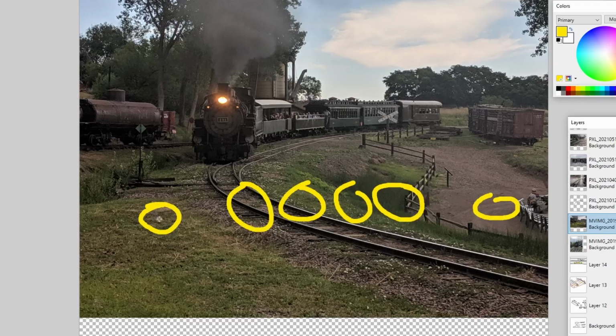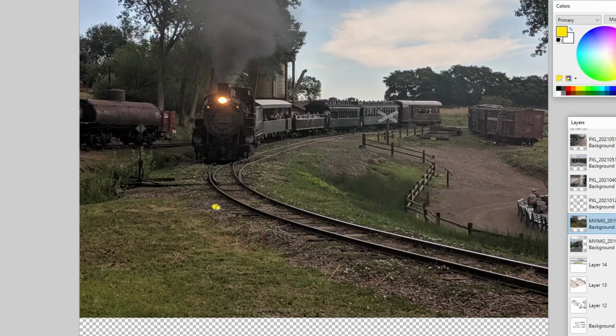It had picked up its lead wheel on the inside edge of the curve, almost an entire foot off the top of the rail, because the suspension ran out of travel because the curve got so tight. The suspension was trying to keep all the wheels in contact with the rail, and it couldn't do it. It ran out of travel, and it just propagated forward, and all it could do was pick the wheel up. And so it was literally holding the inside wheel. I mean, it was a good 8-10 inches off the top of the rail. The wheel was up here. I've never seen anything like it. But that's what happens when you don't have proper ballast.